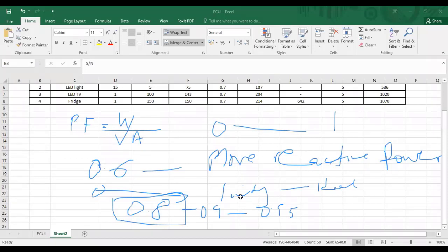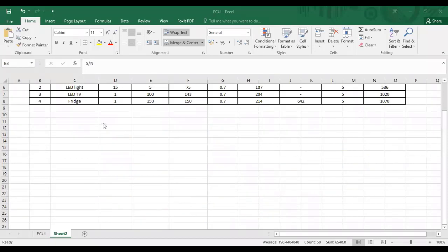Sorry for that. Like I'm saying, except for good inverters, that have their power factor close to unity, most of the inverters, you have 0.7 and the like. So we have to be very careful about this. When trying to choose an inverter, always try to go for an inverter that has a good power factor. But the good power factor will always come at a cost.